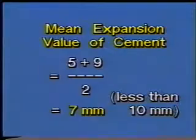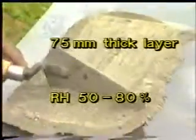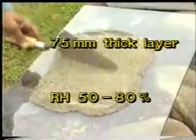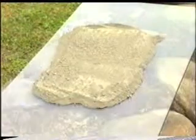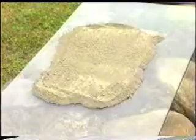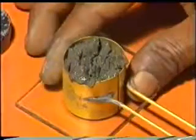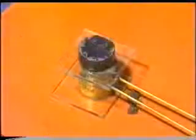In the case of unsound cement, the aerated cement test is carried out, which involves spreading out the cement in 75 mm thick layer in an atmosphere of relative humidity of 50 to 80%, maintaining a temperature of 27 plus or minus 3 degrees Celsius and keeping it for 7 days. Retest this aerated cement sample.